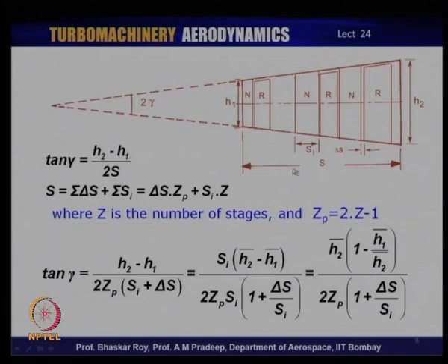So, we have the shape size of the actual length of the entire turbine multi-stage arrangement, and as you can see here, that is going to come into picture in deciding what this conical angle should be. And then of course, the number of stages would have to be decided, as we have done in the previous lectures. The number of stages would have to be decided by certain aerothermodynamic considerations.